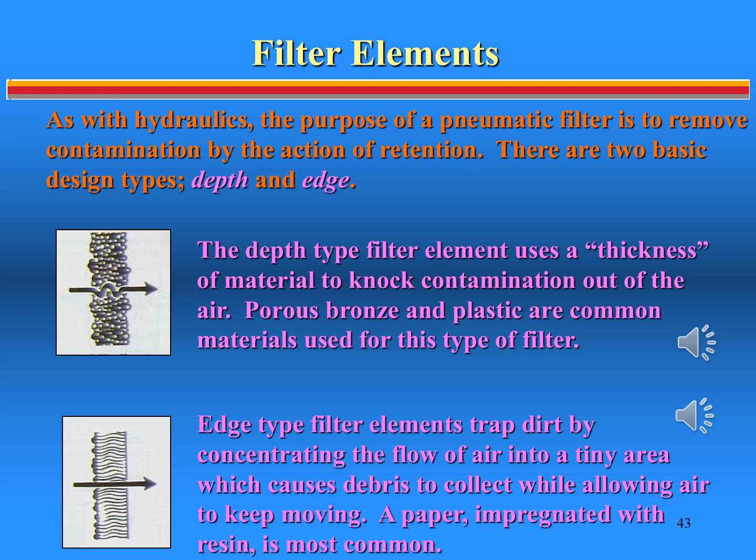Fluid particles such as condensate or oil coalesce or attach to larger droplets, which flow off and are caught in the filter bowl. It is important to cascade your filters to avoid prematurely clogging the filter element. For example, if a 1 micron filter is needed, it is recommended to use a 5 micron filter upstream so that the 1 micron filter does not become clogged with larger particles.